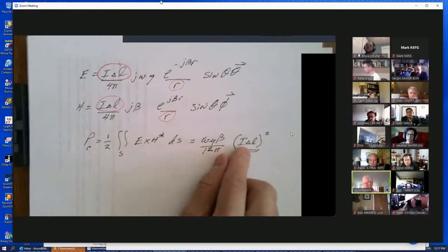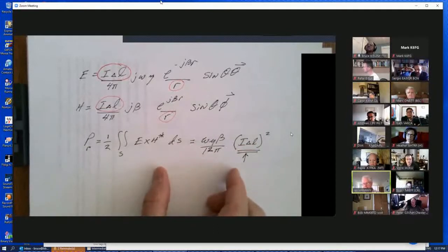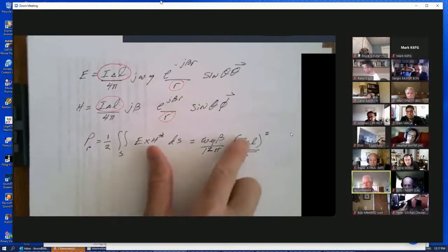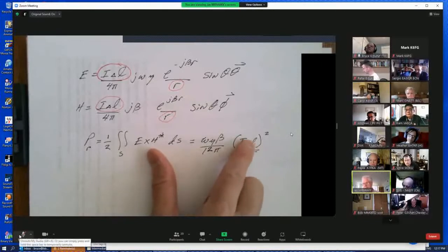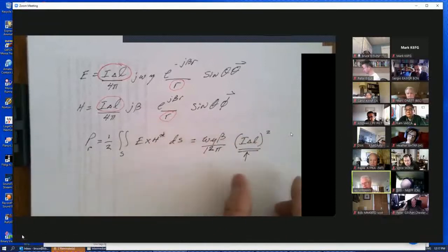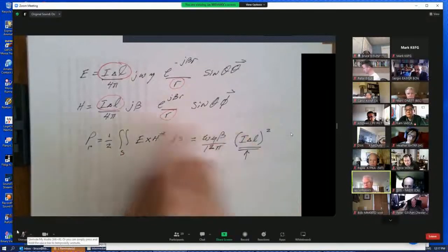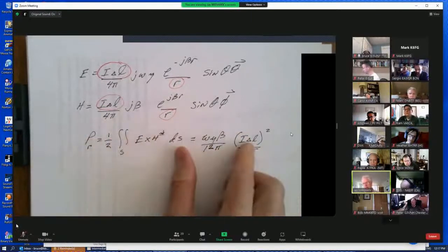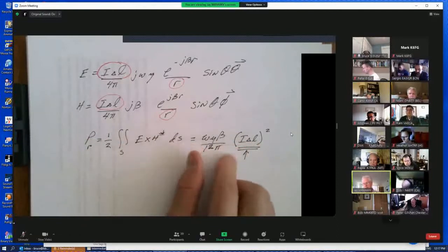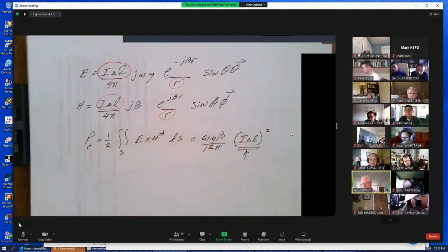Does everybody understand this? We're getting a little bit into the math. This is assuming you've got your little 6-inch section or your 3 centimeter section of incremental length, and it's got a certain current in it. Notice this is under the square here as well. As you add those up, each one of them contributes to your radiated power. And that's where part of the discrepancy comes from. Like I said, it's the current distribution.